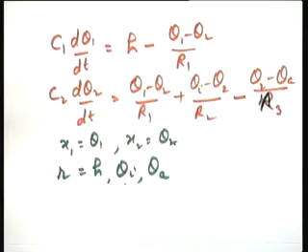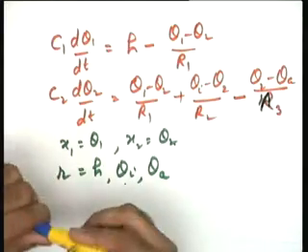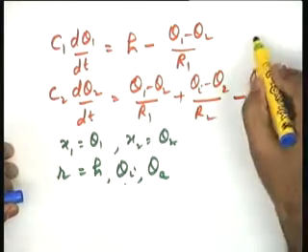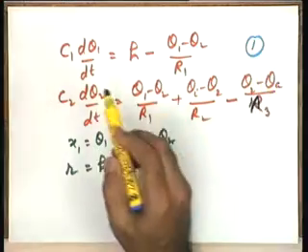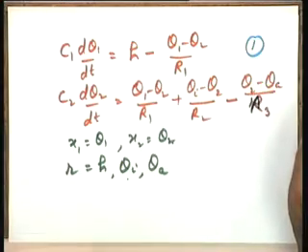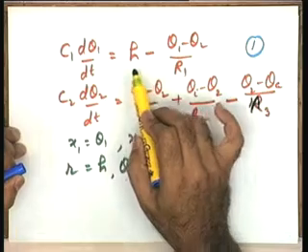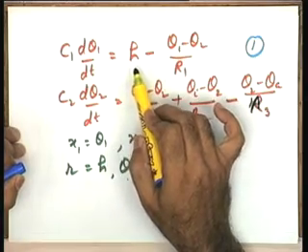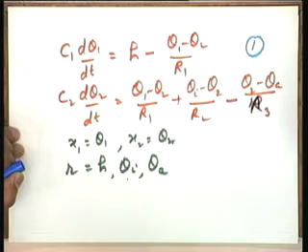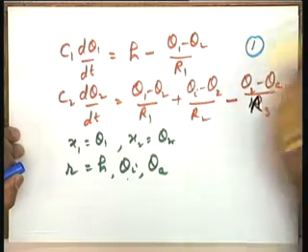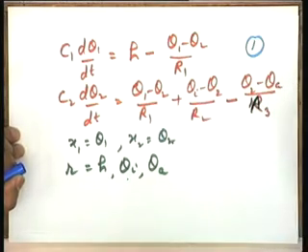If you take the heat storage equal to 0, in that particular case please see the equation 1 gets modified to, the left hand side becomes equal to 0, it gets modified to H, the controlled heat, is equal to theta 1 minus theta 2 by R1. Under this assumption this becomes your equation, H is equal to theta 1 minus theta 2 by R1.